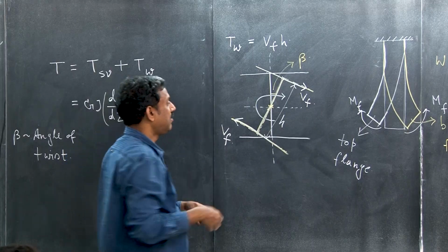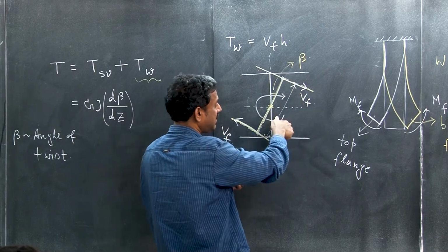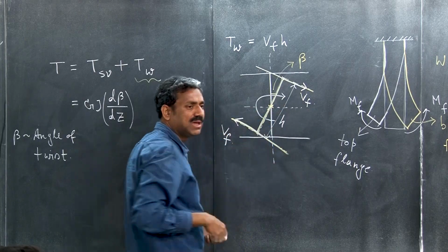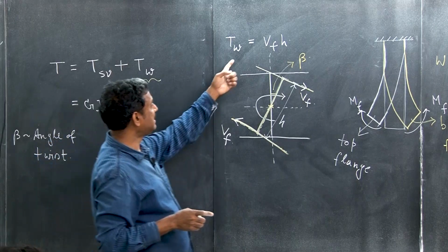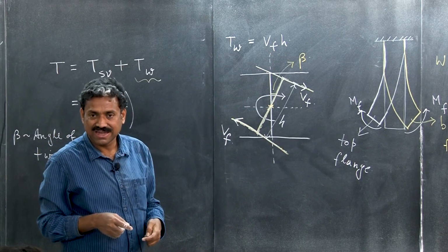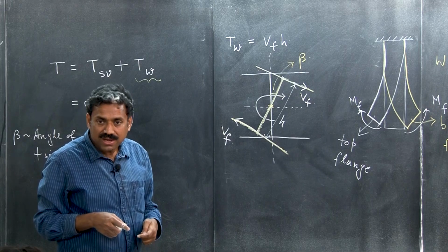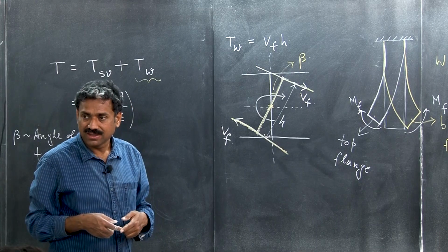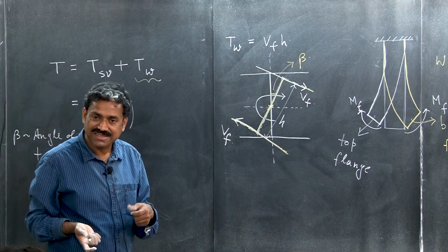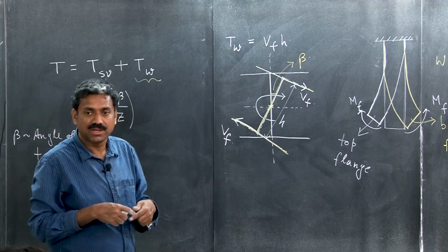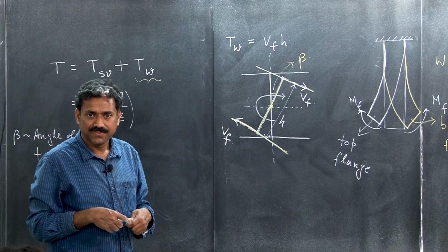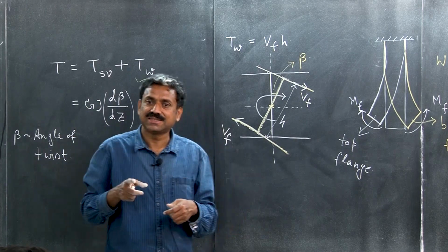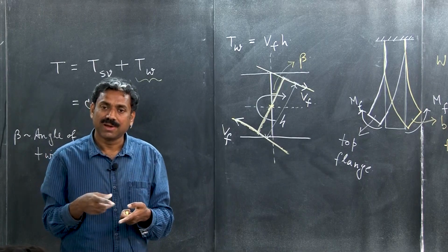You understand that? Now, you may say, sir, why is it also coming in this direction? It is nothing basically; if it is externally applied in this direction, then it will be resulting. Okay. So, you do not worry about that. So, you understand how I am getting here the twisting component, the warping torsion, which is basically in action to counteract the twisting, right. You see that. So, the external torque being applied is resisted by Saint-Venant torsion, and in other words by the warping.